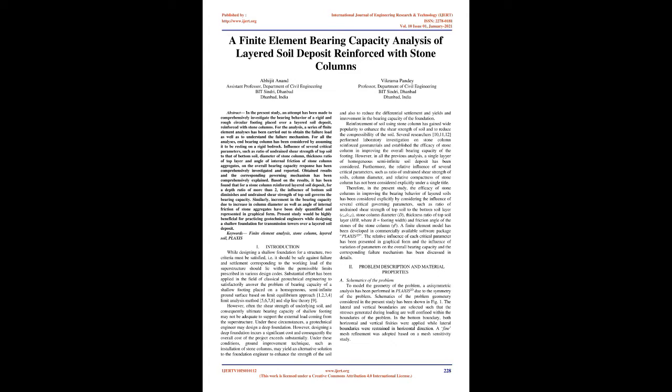Introduction. While designing a shallow foundation for a structure, two criteria must be satisfied, i.e. it should be safe against failure and settlement corresponding to the working load of the superstructure should lie within the permissible limits prescribed in various design codes. Substantial effort has been applied in the field of classical geotechnical engineering to satisfactorily answer the problem of bearing capacity of a shallow footing placed on a homogeneous, semi-infinite ground surface based on limit equilibrium approach 1, 2, 3, 4, limit analysis method 5, 6, 7, 8 and slip line theory 9.